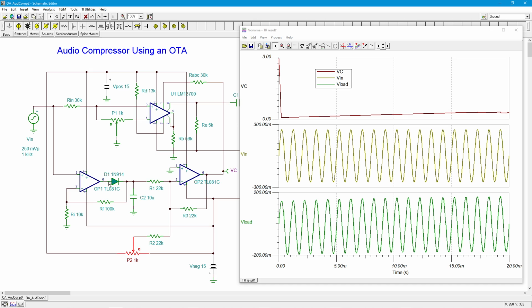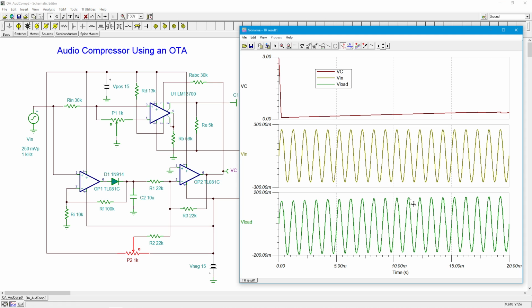Now, as the input signal comes in, this rectifies it. What we're seeing here is this capacitor jumping to that value, and then over time it kind of levels out. This is not much, pretty close to 0 volts. We're at this essentially halfway value on the gain, because we could crank VC all the way up to nearly 15 volts, my power supply rail. Not quite, but close to. So we're right in the middle. But in any case, let's check out what our gain is.